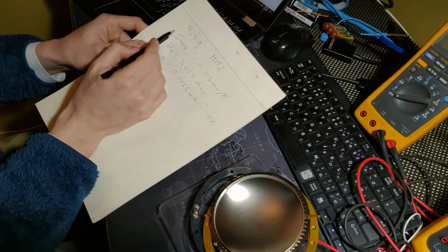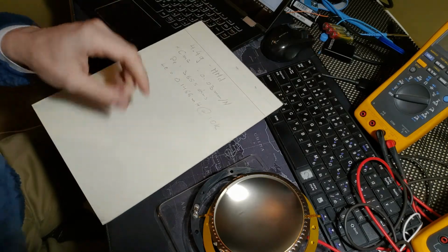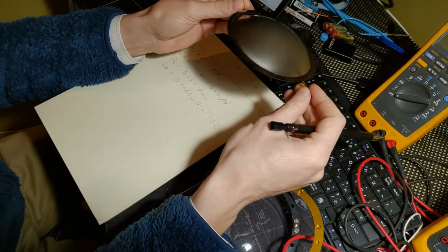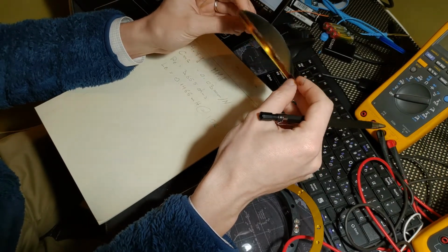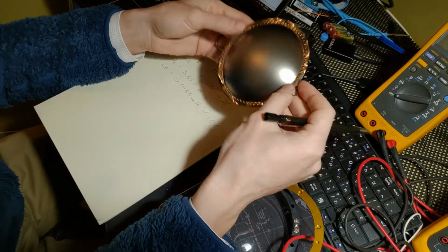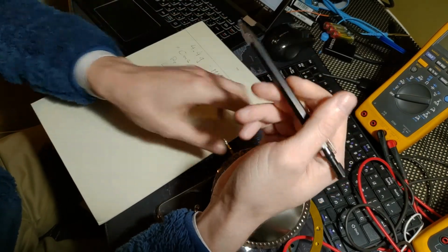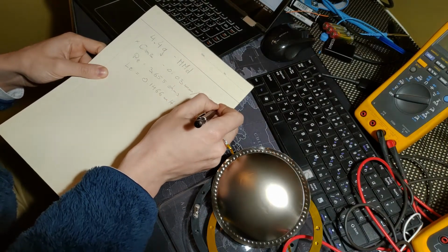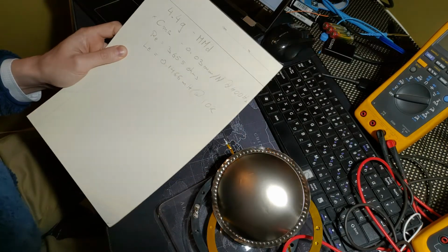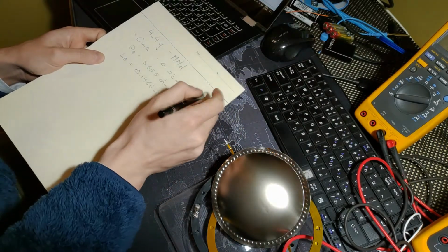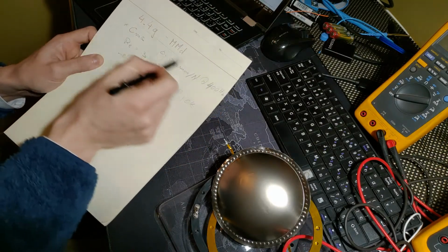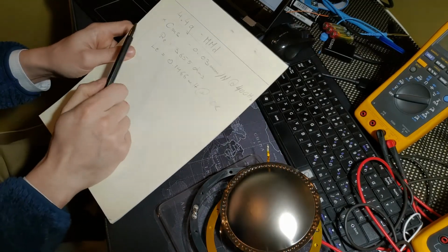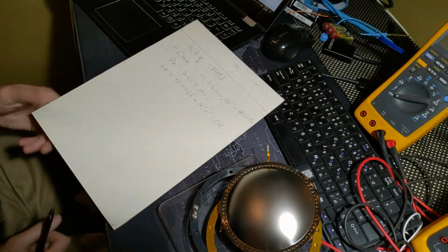The hardest one to get is the actual CMS. So what I did is I created a little magnetic circuit and placed this in a magnetic circuit, and if you run an impedance sweep, you will see the resonance. Once you find the resonance, which I think was around 400 hertz, and you know the mass because you can weigh it on a precision scale, then you can easily determine CMS values.